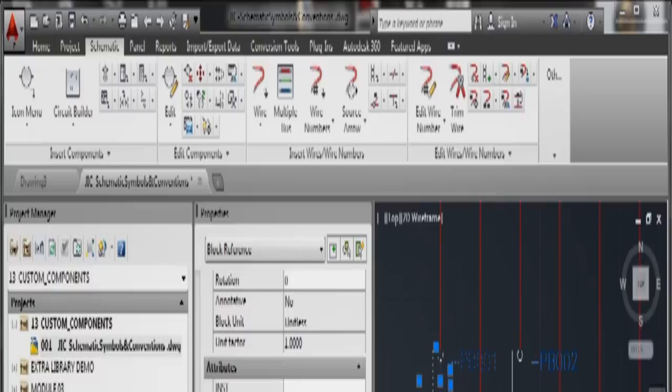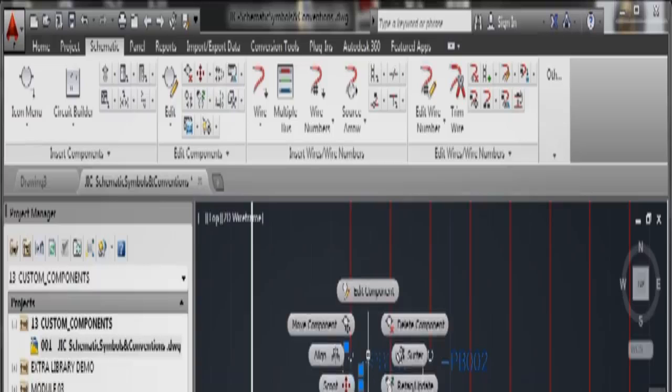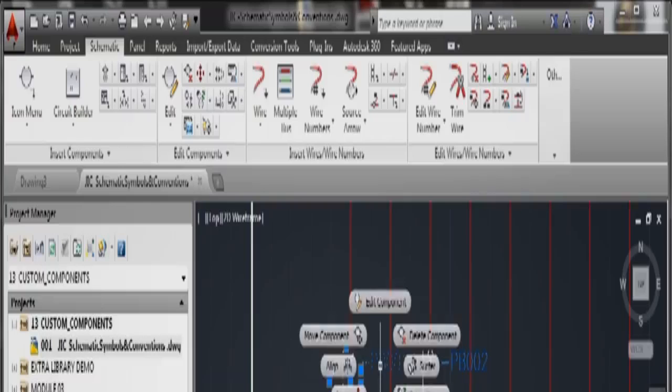This is actually quite unwieldy though, but what you can do, I'll close the properties palette to get the screen back. With that push button selected, I'll right-click, and I can go to Attributes on our little flashlight system. I can list edit like that, and there are all of the attributes. If I tick Edit Attributes, I can edit them that way. If I select the push button again, right-click and go to Attributes, and just do Edit Attribute,